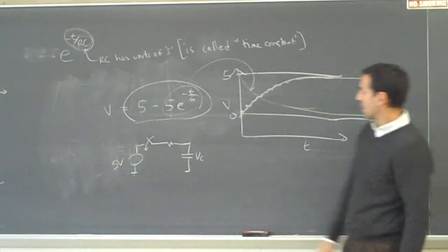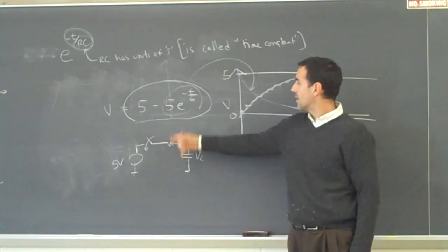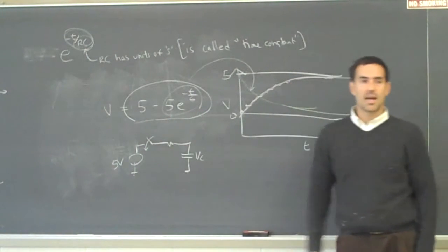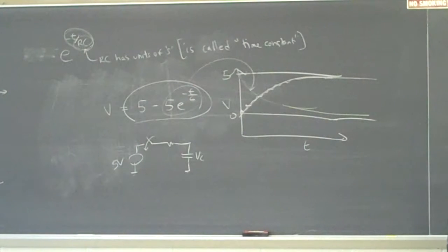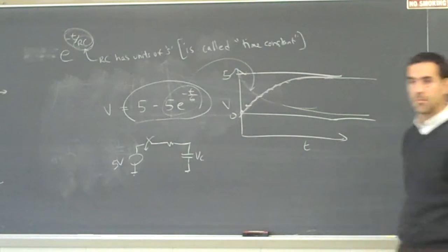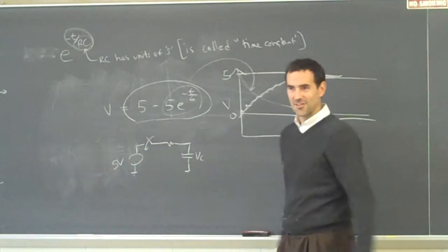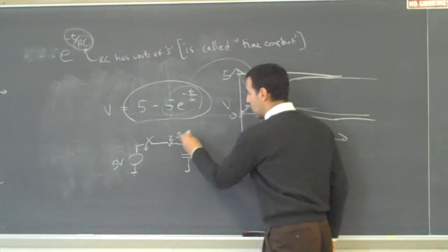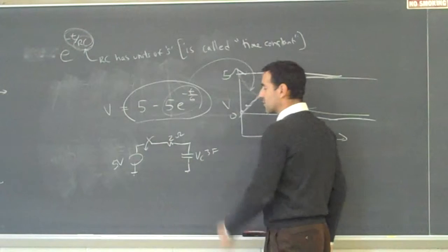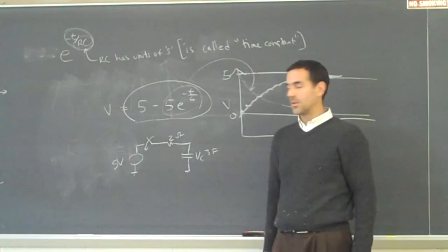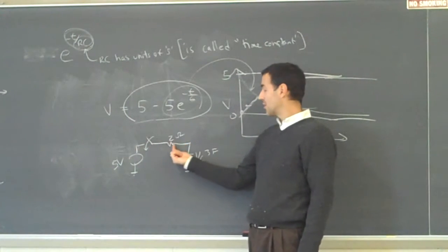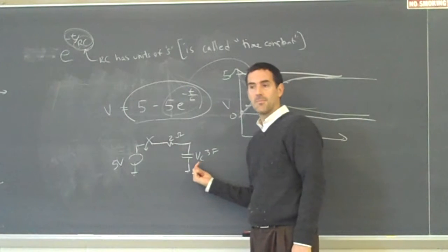What combination could I use for R and C to make it fit this equation exactly? 2 and 3? Which way? Doesn't matter. Correct answer. Doesn't make a difference. 2 ohms, 3 farads will charge up just as rapidly as having 3 ohms, 2 farads.